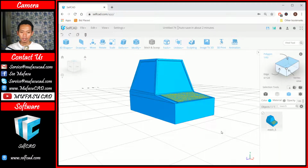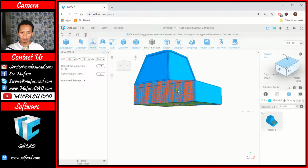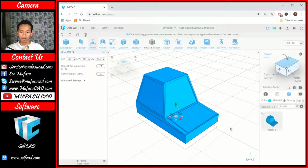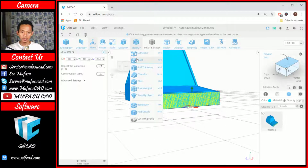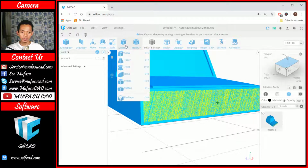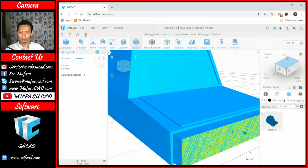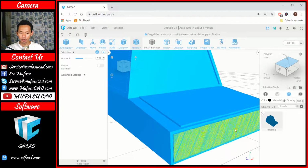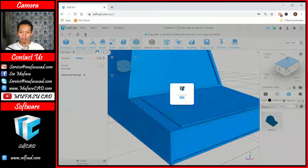Okay, the last I will select this face. Now we can use the move tool. I will move to the top in the green axis into this point. Okay, I will select this face, and we can use insert again. The next we can use extrusion, confirm change, and I will extrude into this point. Okay, you can click OK.